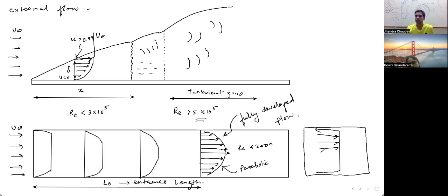They will look like a straight line, and the fluid near the surface will have almost infinitely less velocity. Such profiles are called logarithmic profiles, where almost every particle has the same velocity. You can imagine in turbulent flow, because the particles are not maintaining their layers, all the particles flowing will have similar velocity, except the particles near the surface.